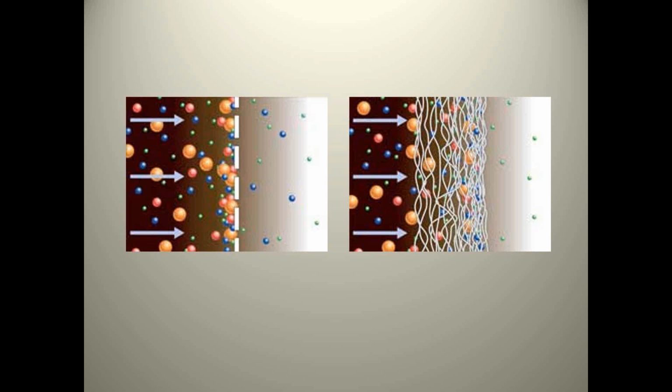Sometimes you'll have vendors come in and they have stainless steel screens and they'll tell you they're high beta rated numbers. Well, you can't get the high beta rated numbers with stainless steel screens, especially the ones that are cleanable and reusable. So don't be trapped into buying things that won't get the results you want. It has to be this synthetic media, lots of hairs, lots of fibers that capture these particles.